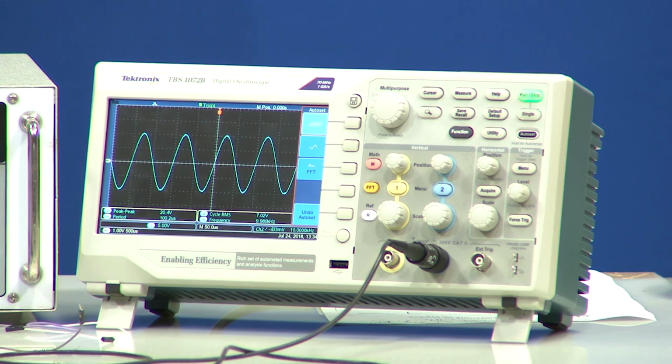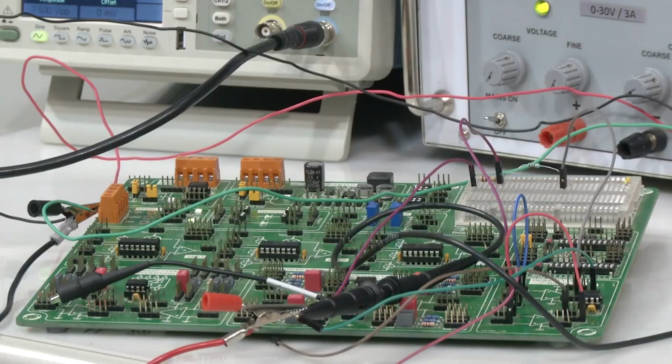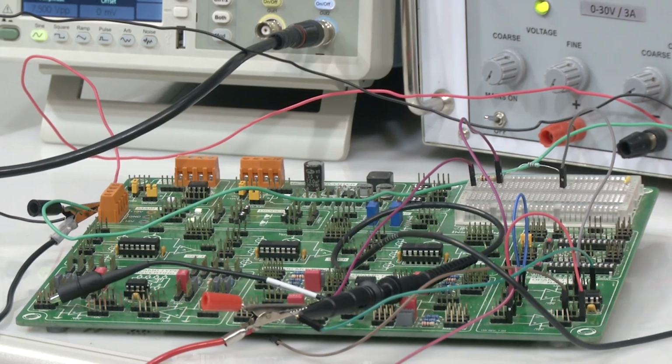That is why the range of an amplifier is an important concept to understand, and you need to absorb it before you delve into more complicated circuit design. One part we have seen as an experiment, where we changed the amplitude of the input for different gains and saw at what amplitude the output starts getting clipped off. That is one story about the range of an amplifier. Another aspect of the range of an amplifier, which the professor has discussed in the class, is about the input frequency.